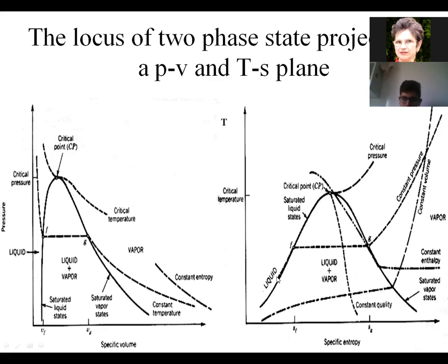So let's take water, liquid, warming up, vaporization. This horizontal means that at the same temperature, liquid and vapors share the same temperature and form a mixture in equilibrium. Here in the left point, we have only water at saturated temperature, and here in the right point, G represents only gas, saturated gas. And heating up at constant pressure gives superheated vapors, gas.